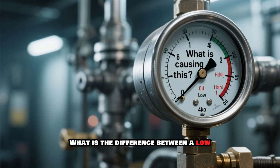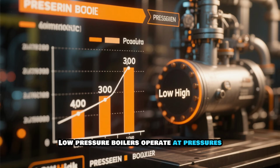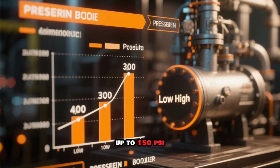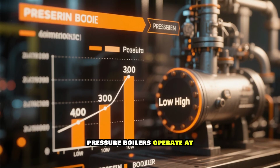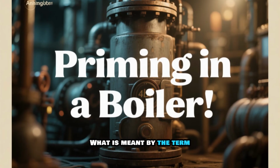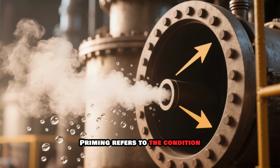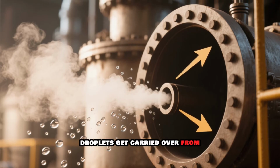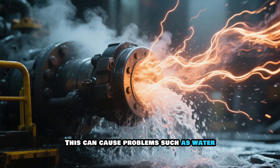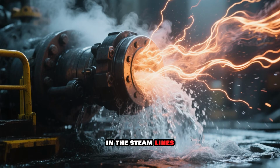What is the difference between a low-pressure boiler and a high-pressure boiler? Low-pressure boilers operate at pressures up to 150 psi, whereas high-pressure boilers operate at pressures more than 150 psi. What is meant by the term priming in a boiler? Priming refers to the condition in which the feed water droplets get carried over from the boiler drum along with the steam. This can cause problems such as water hammer and carry under in the steam lines.